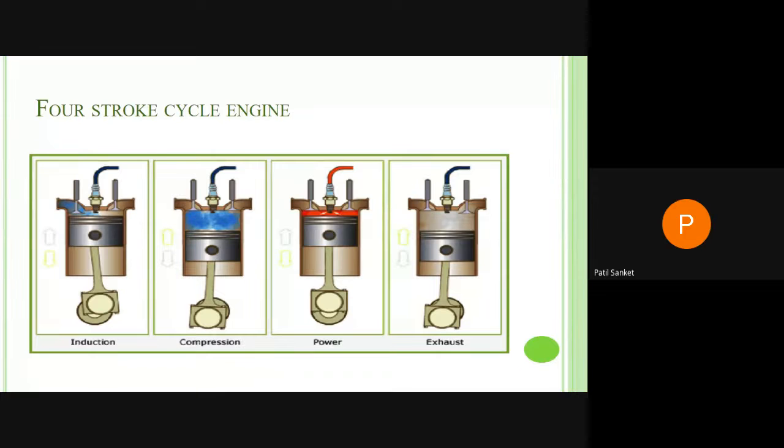Okay. See, if we use diesel in a petrol engine, diesel is viscous in nature. That means you can't convert it into fine droplets. If there are no fine droplets, that means you can't ensure proper mixing. If there is no proper mixing, what will happen? The spark plug is going to spark only at one place. Will it spark in the corners? No, it won't.